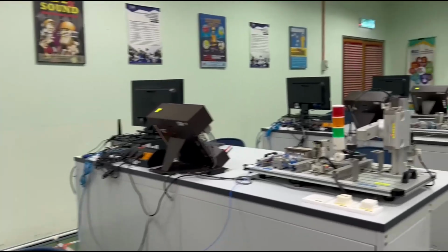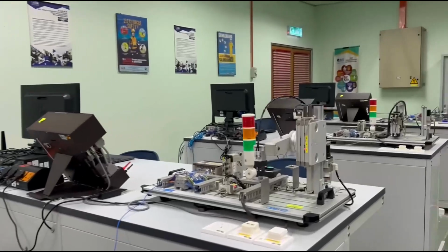Assalamualaikum. I am Ahmad Mulhim. I will talk about the functions of MAP 203. For MAP 203, A is the rotary actuator, while B is the gripper arm. The sensor has three positions: A0, A1, and A2. The initial position is A on sensor A1. The input signal is from port 0.10.